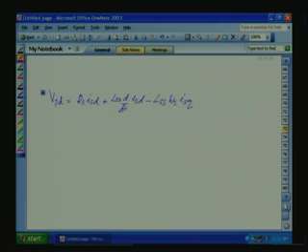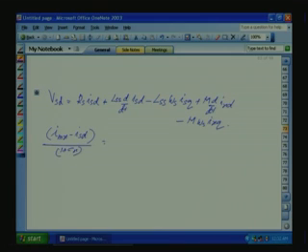So it shows VSD, there's an ISQ. Any change in the ISQ component will reflect on VSD, plus M into d by dt IRD minus M into omega S IRQ. See, the IRD, IRQ terms, the rotor currents, we can represent in terms of ISD and ISQ. We know that IMR minus ISD divided by 1 plus sigma R is equal to IRD.